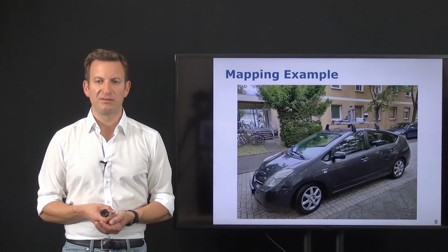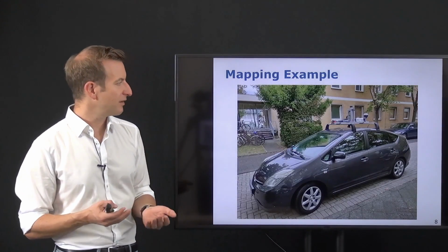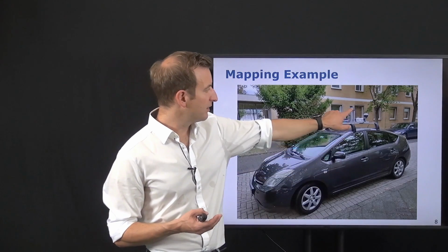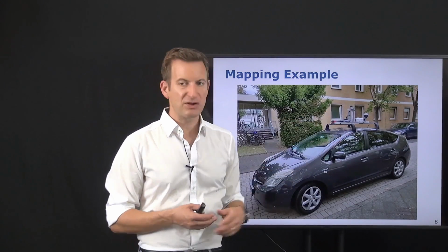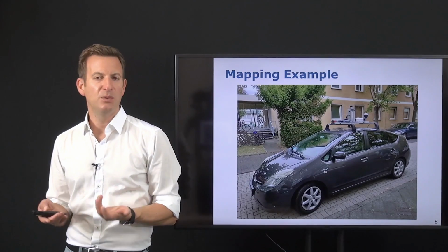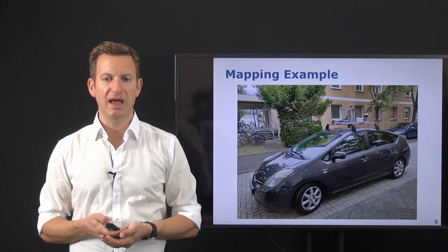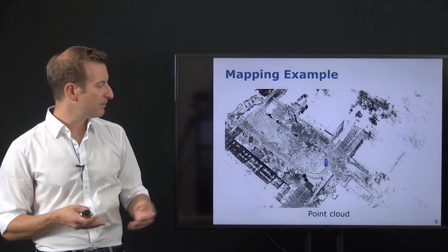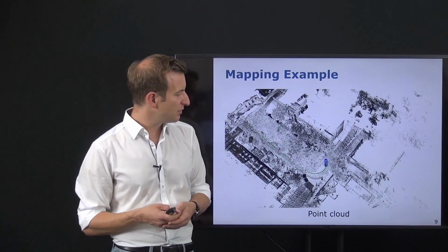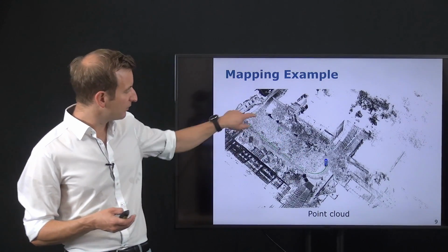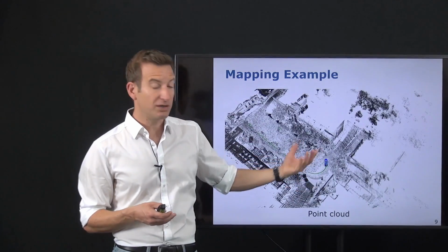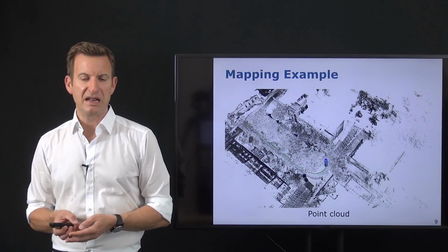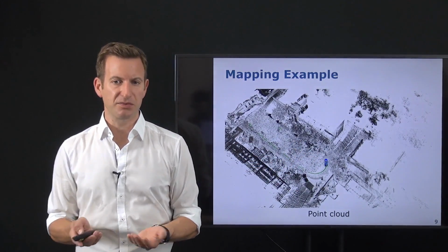This also becomes relevant for autonomous cars. You have a vehicle, like this vehicle over here, which is equipped with cameras and laser range scanners on top of the vehicle. We can actually drive around here on campus and build a map of the environment. This is a 3D representation of our parking lot here in the back, and you can see the vehicle which was driving around and building that map from the 3D LiDAR data while navigating through the environment.